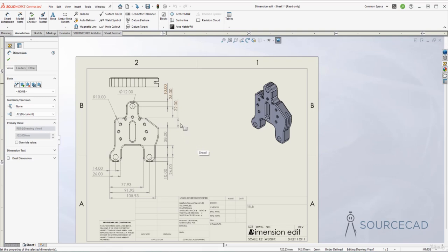Now you can also change even more properties. Now in this case, look at this. These arrows are right inside this drawing, but let's say we don't have enough room for adding arrows inside. In that case, you can select it and click on these grips. When you click on these grips, the arrow direction will reverse. Now the arrows are outside. If you want to once again bring it inside, just click on the arrow and the direction will reverse.